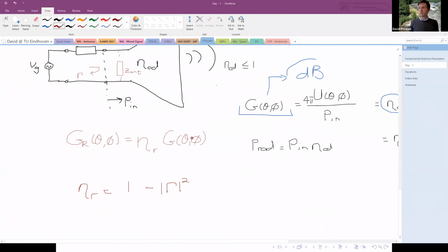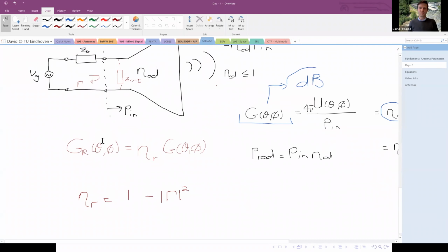And so Pierce, I hope that answers your questions with regards to the impedance. That is only when you talk about the realized gain do you take into account the source. So all other references are from the port of the antenna onwards, accepting or working with the power accepted by the antenna, and then either assuming losses or not.